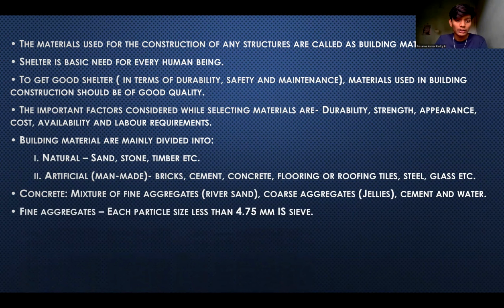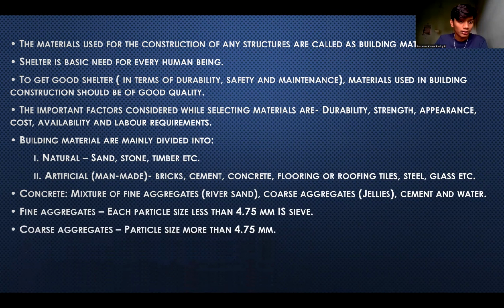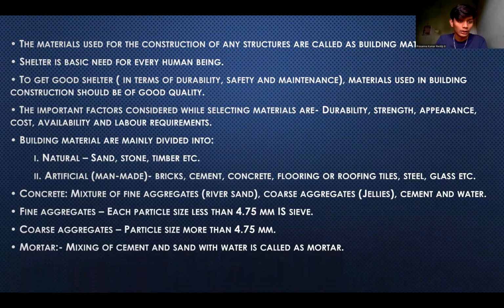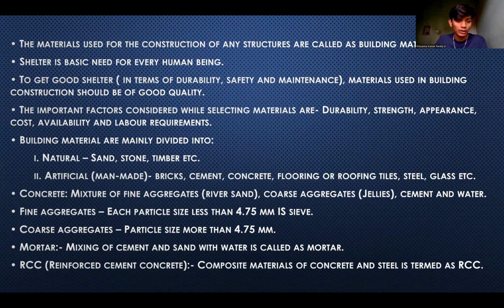Fine aggregate: each particle size is less than 4.75 millimeter in sieve. Coarse aggregate: particle size more than 4.75 mm. Mortar: a mixture of cement and sand with water is called mortar. RCC, reinforced cement concrete: a composite material of concrete and steel is termed RCC.